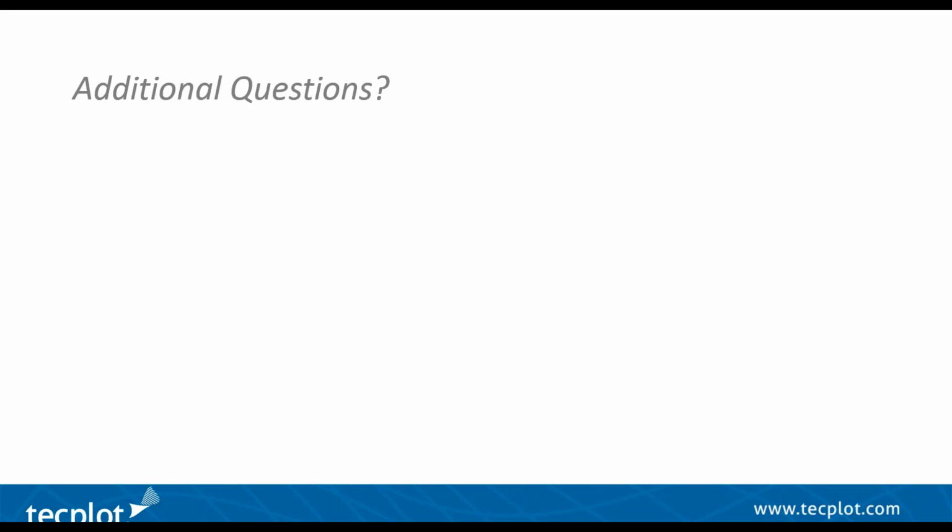Okay, I think the question is actually slightly different. He's asking how to calculate forces and moments, I believe, from the surface. Basically, how to calculate forces and moments when you have volume and surface data. That would also be under the Analyze menu. There's a forces and moments calculation there. Right, under the integration. Integration, yeah. Under forces and under the Analyze menu.